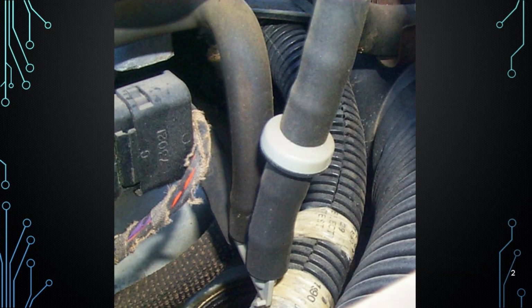That cylindrical piece connecting the hoses is likely a vacuum delay valve. These valves are designed to delay the passage of vacuum for a set period of time. They're often used in emission systems like delaying EGR operation or delaying vacuum advance on the distributor. Its purpose is to ensure a timed vacuum response rather than immediate.